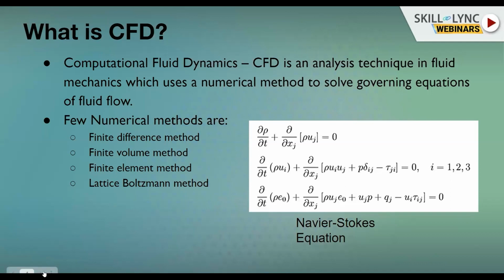That's where it becomes critical. And it's not just the Navier-Stokes equation. We do some kind of dynamical approximation. For example, the Euler equation, which doesn't use the shear stress term, is also solved under CFD, and sometimes the potential equations. So a lot of different kinds of equations can be derived with different approximations.